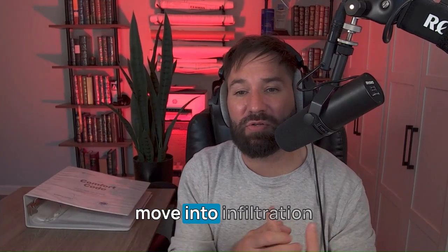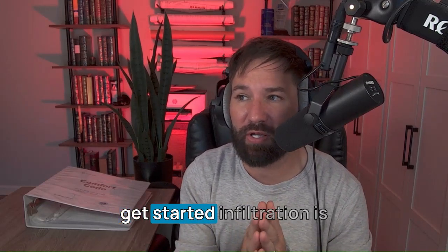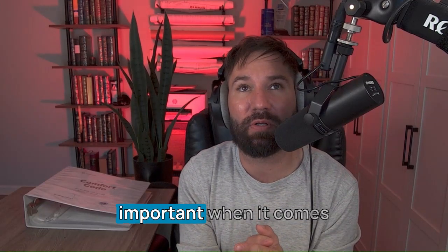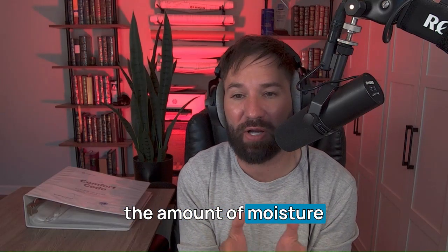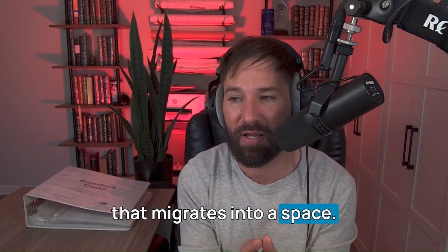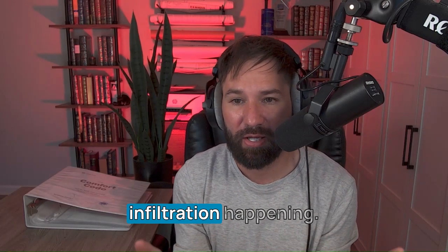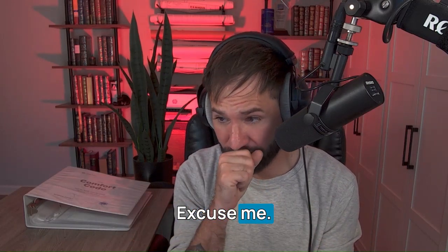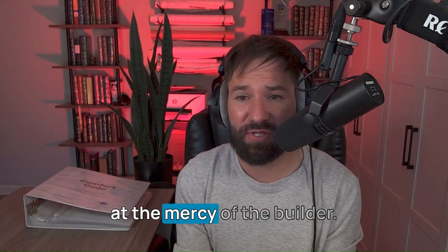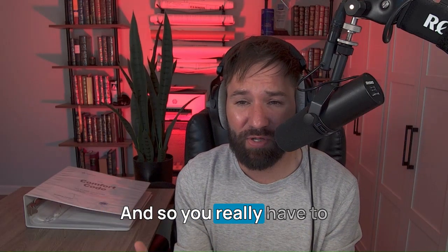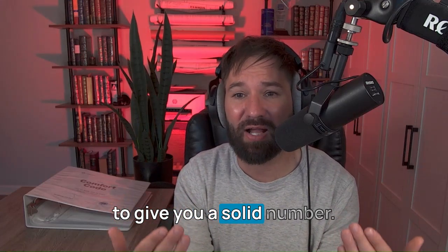Okay, so now we're going to move into infiltration and ventilation. Real quick before we get started, infiltration is important when it comes to energy efficiency and the amount of moisture that migrates into a space. You have no control over the infiltration happening in a home. You're completely at the mercy of the builder. And so you really have to communicate this well with the builder for them to give you a solid number.